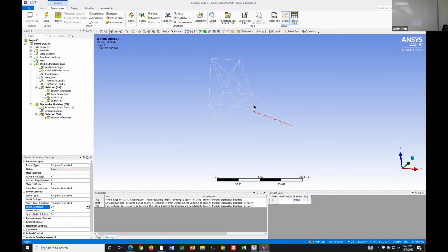But in a true buckling test, you only have a compressive mode. That's kind of true. So if you take out the transverse load, your structure can sustain more load. So the buckling multipliers are increasing. Right. And so that means that you can increase your load by more before it buckles. Okay, yeah.